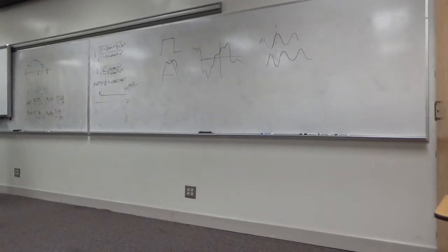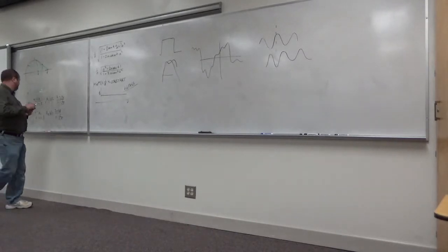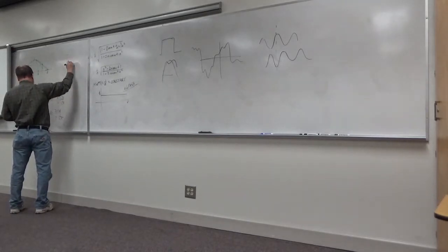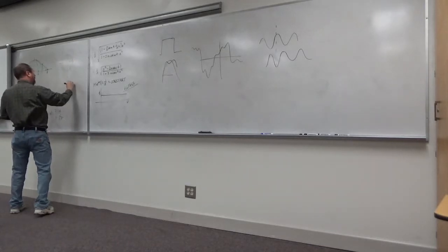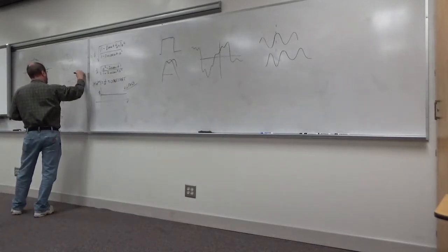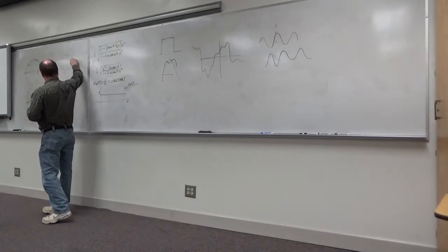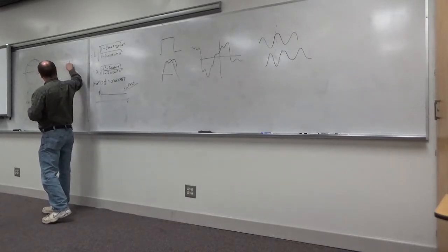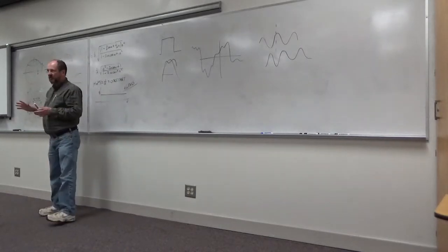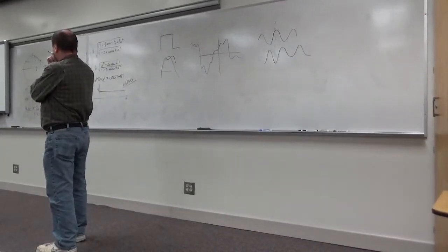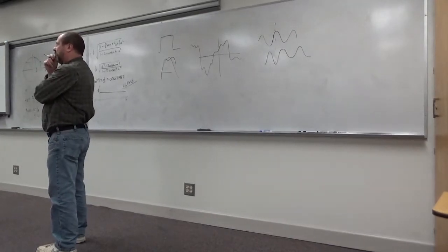Those have, let's see, we're starting, the very first one has a 0 here and a pole there. That's kind of a high-pass filter, isn't it? Wouldn't you agree? You start out over here closer to the 0, and as you go around, you wind up closer to the pole. It's not a great filter of any kind, but it's kind of a high-pass filter. Okay, turns out every one of those will have that same response.